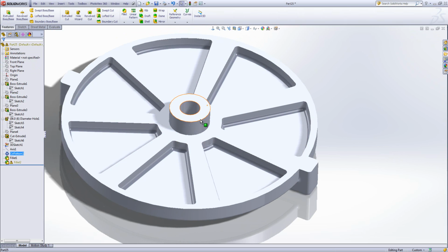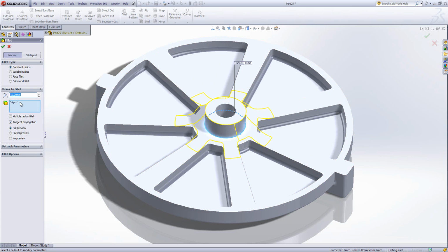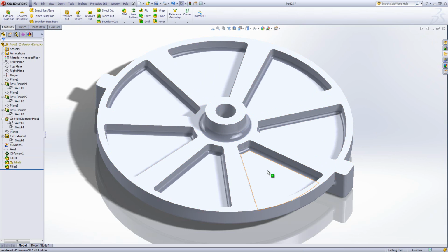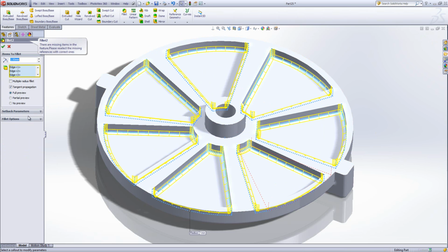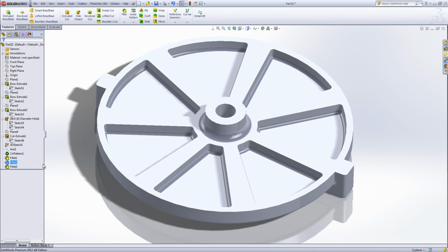What it essentially allows us to do is go into a design like this one and be able to make changes to it where we couldn't do before a lot easier. We could add, say, a fillet back onto this edge at a certain size to actually finish that off and get it back to how we want it. And you could just adjust this fillet to then remove any missing edges within here. And that gets rid of any problems.